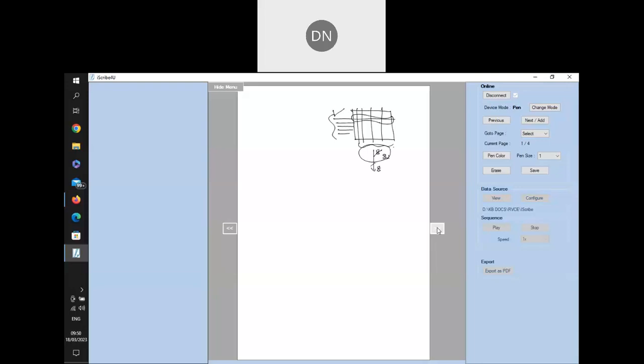So sometimes along with the decoders, there is an output multiplexer, which selects from the 32 a particular byte, and also a demultiplexer used when you want to write 1 byte to a particular location. So this concept is also used in some of the memory chips. Now we will study the static memories, how the static memories are built.